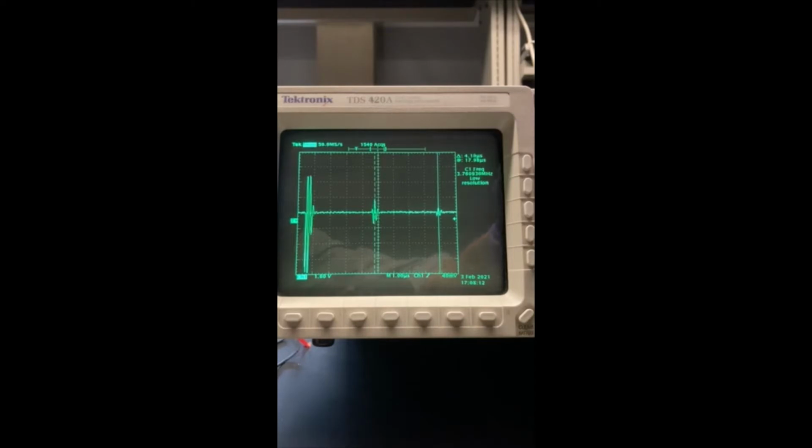So we're determining the same pulse or peak shape each time so that we can get accurate measurements of the pulse time delays. As you can see, determining what portion of the pulse to put the cursor on is a tricky undertaking and may lead to additional errors.